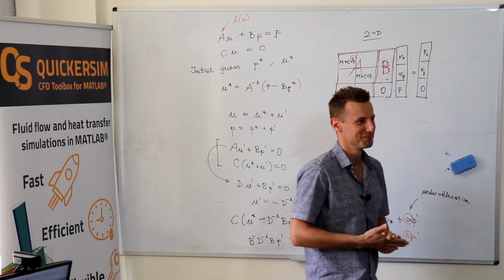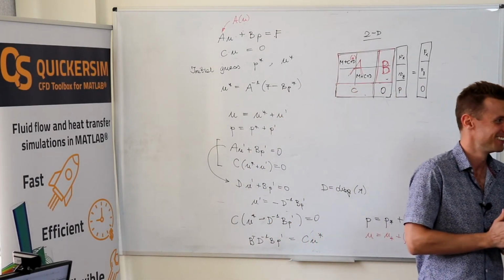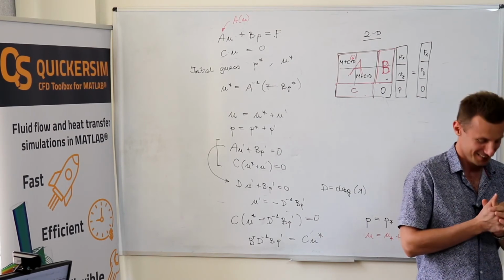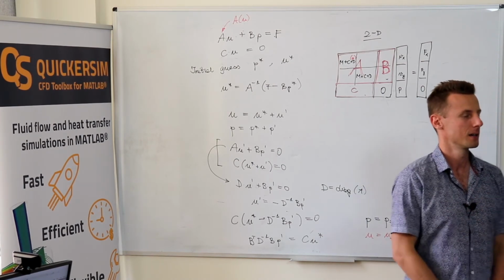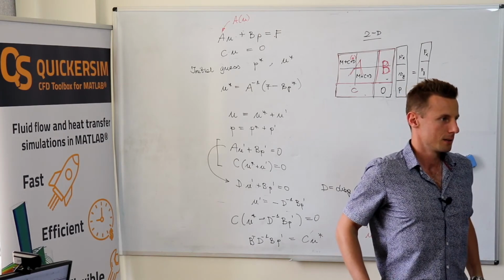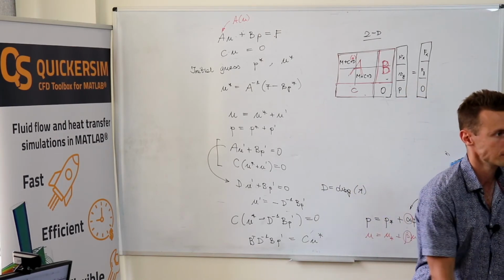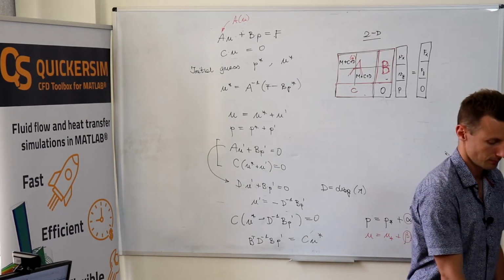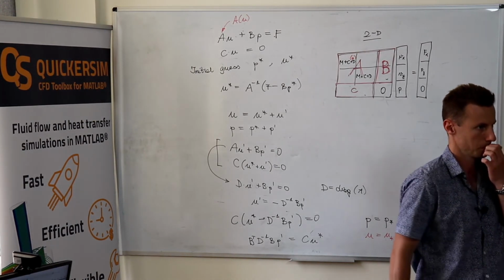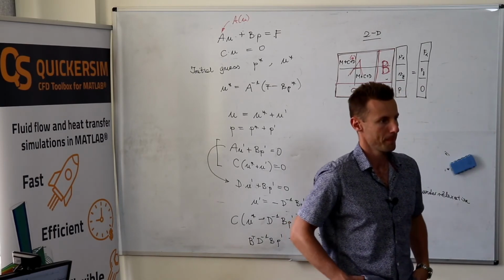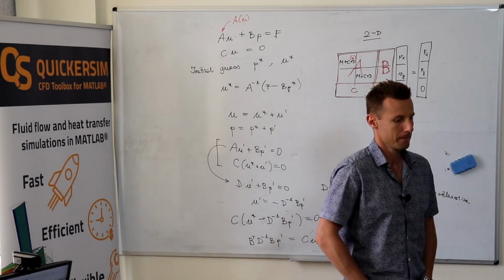Yeah, question. Okay, because in the SIMPLE algorithm, we still solve that version of our equations with the equation that states that the divergence of velocity field is 0, and we just made a different attempt to solve this.